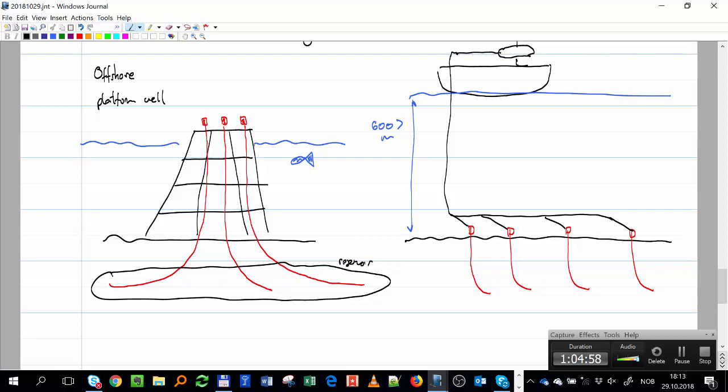That happens if you have higher depth. Also, if your reservoir is very spread or you have different accumulations, you cannot drill all wells from the same location. So you have to use a network type approach, which I already mentioned. With the standalone wells, each one behaves separately. They are king, they are on their own highway, they can do whatever they want, unless there is traffic, right? But here you have a lot of interaction between the wells. So with that we have to be careful.